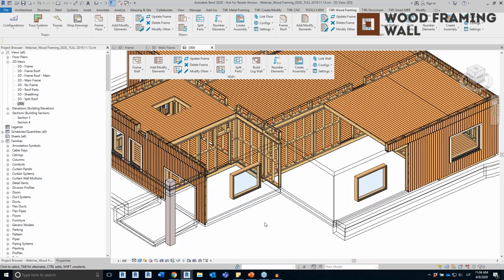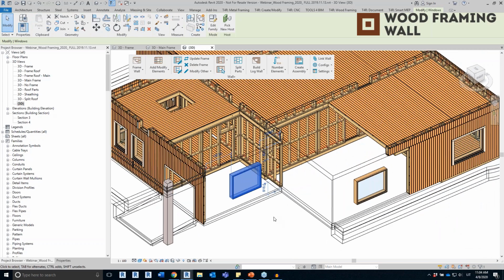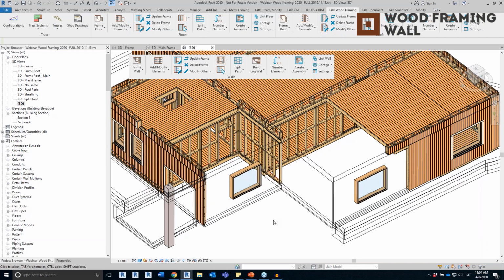So before I start, I'd like to mention that it's important how the model is created. The walls have to be the same size as the future prefabricated panels, so you should split them if you need that. Also, you need to pay attention to the height of the wall, and the software will identify all of the openings, whether they're windows, doors, or MEP openings.